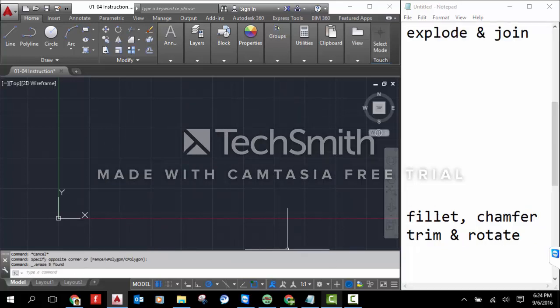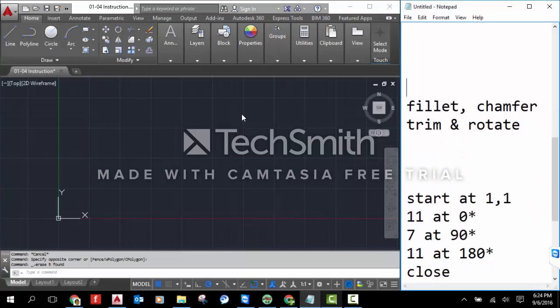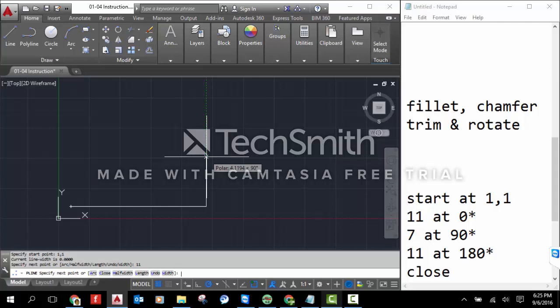Now we're going to look at how to fillet, how to chamfer, trim, and rotate. What we're going to do is begin by drawing a rectangle using our polyline. We're going to click on polyline, and we're going to specify our first point, 1,1. Remember, it acts just like a line. We're just going to use it, and it's going to help us put it all together. We're going to go 11 at 0, 7 at 90, 11 at 0, and then we're going to close.